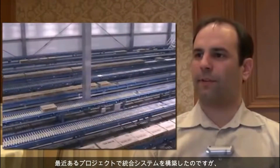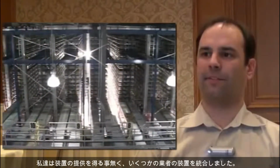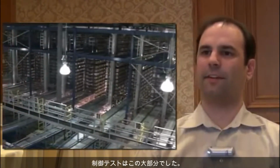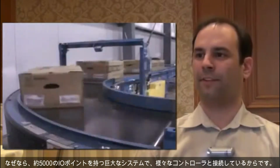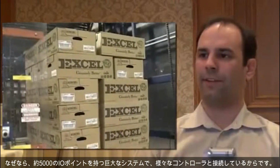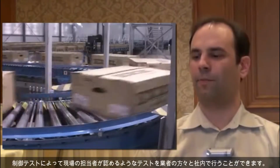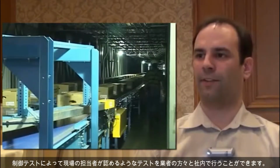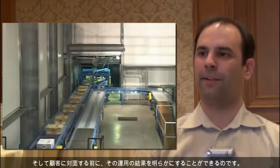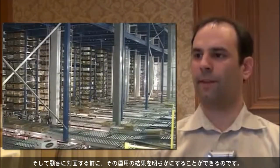In a recent project, we were assembling an integrated system where we're not supplying any hardware, but we're integrating hardware from several vendors. And controls testing was a big piece of this because it's a large system with about 5,000 I/O points connected to various controllers. And we don't have the time in the schedule to go on site and fight it for months. So what this allows us to do is almost do factory acceptance testing in-house with the vendors and their controls people and prove out all of their applications before we ever go in front of the customer.